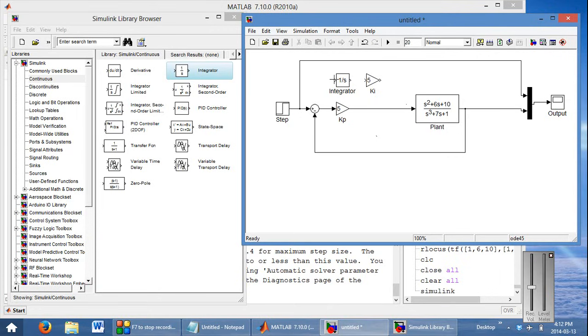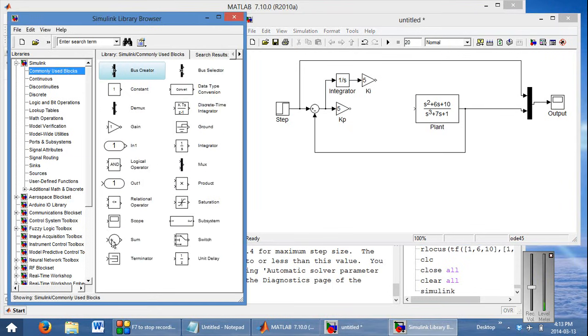So now all we have to do is grab the error and connect all of these blocks. So now we need an additional summation junction in between so that we can add signals from KP and KI. So let's delete the signal and grab a summation block.